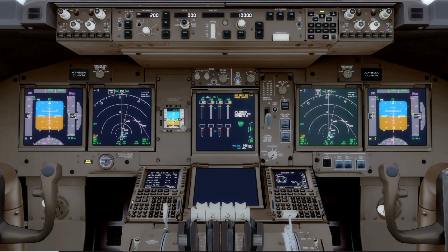And then we come over here to the ISFD, check that. Brightness is desired, 30 knots parked. It's set to the 2980 field elevation. No flags again, and usually we don't have the approach selected or anything like that. That should also be blank, and so that's good. Check that. Set the altimeter if you need to. I have it set so that when I set the altimeter, it sets all three instead of having to do it individually.